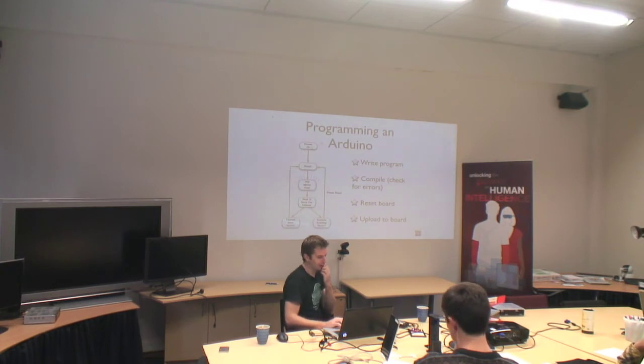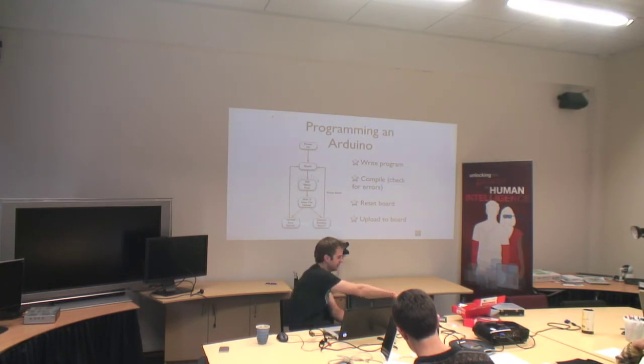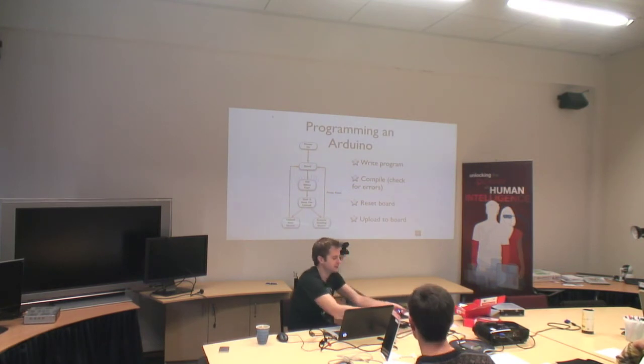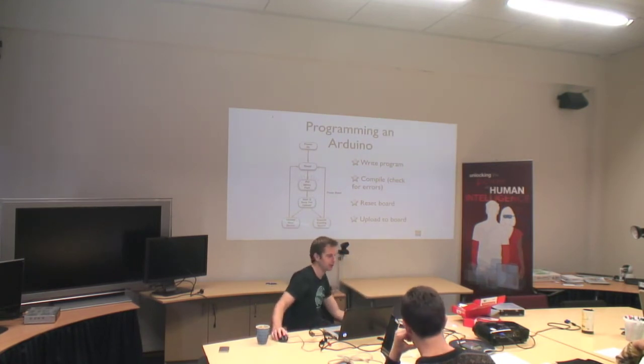So yeah, we power on our Arduino, it resets itself. Pin 13 blinks fast, that's just while it's booting up, and pin 13 is this little light here, the L or loading light on this one. So you'll notice when I plug this in, both this light here and the yellow light will flash quite quickly just while it boots. And then once it's finished, it'll just continue on loading the program. So don't plug anything into pin 13 that you don't want powering on and off quickly when the Arduino starts. Use one of the other ports. Usually you start at 1, and pin 13 is the highest pin number on these boards, so you usually don't use it unless you're running out of them.